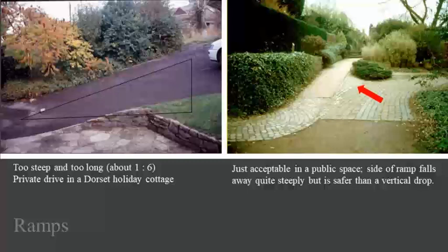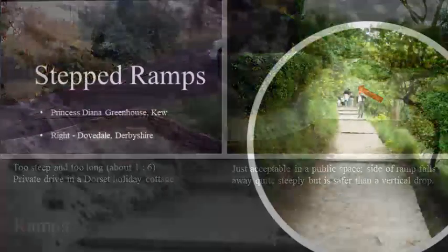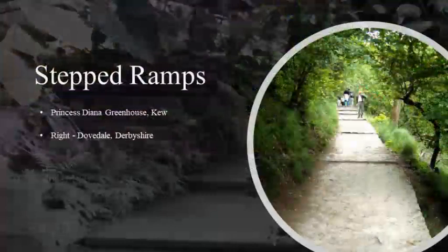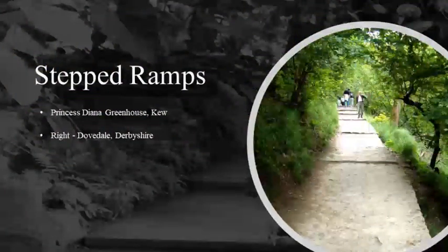Obviously, the 900 millimeter width need not apply to occasional use paths in domestic gardens. In a public place, where 2 wheelchairs or prams may need to pass, the preferred width should be 1.8 meters. If you intend users to take an additional pace between risers, add at least 650 to 700 millimeters onto the tread dimension.